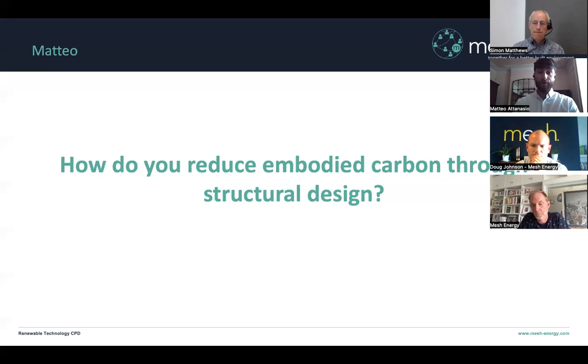So then you've got reuse of material, which is another way to build less by using less material in the things that we're building. Doug touched on reducing the embodied carbon of steel and concrete, and one of the best ways to reduce the embodied carbon of steel is reusing the sections that we already have in circulation. Thousands of buildings are demolished across the UK every month, and those steel sections are typically cut up into smaller sections, sent to an electric arc furnace, melted down and reused.